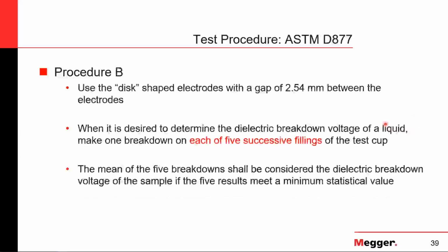There is a factor called test acceptance criteria used for both methods. For ASTM D1816, we have 2 criteria depending on what gap setting we had in our electrodes. Right, I said the unit will calculate a range. So what is the range?